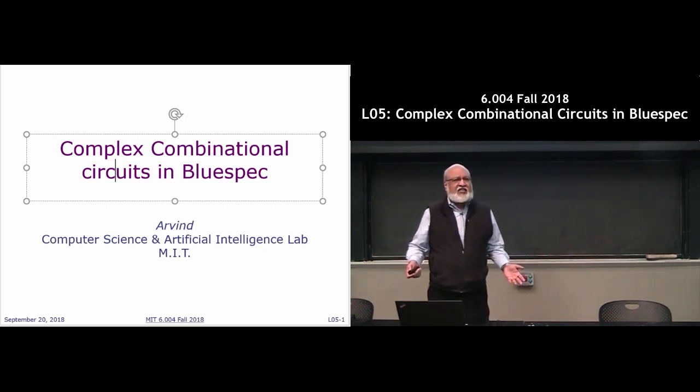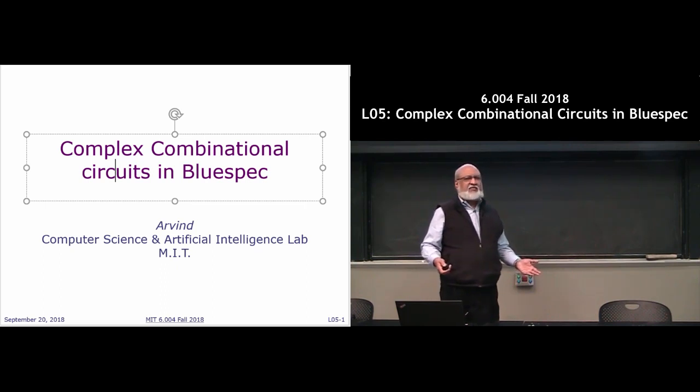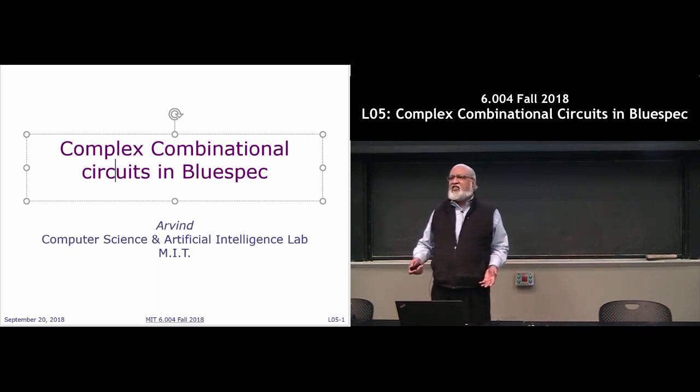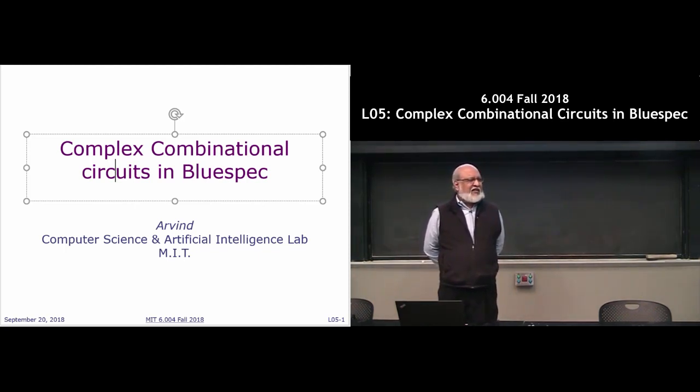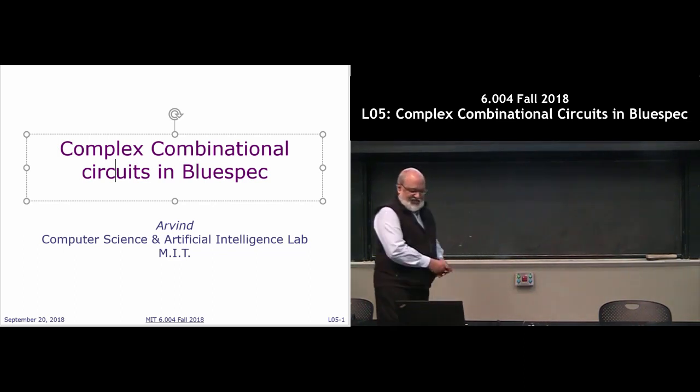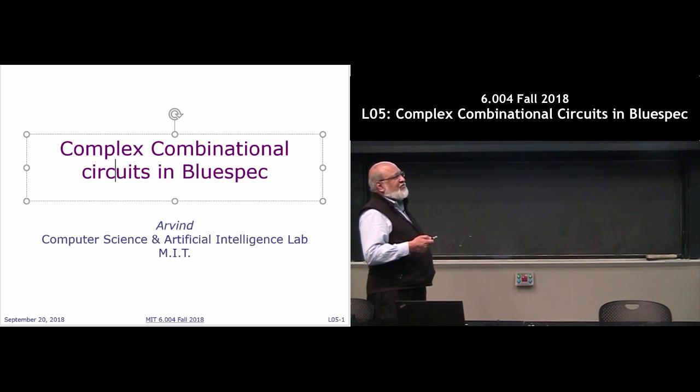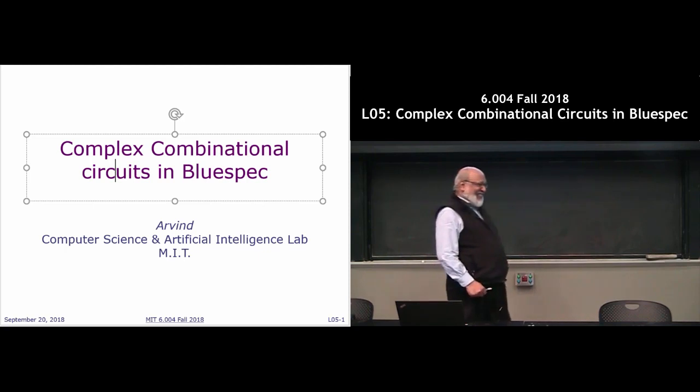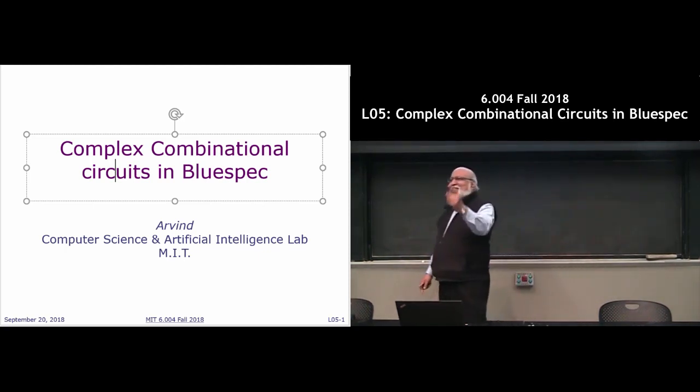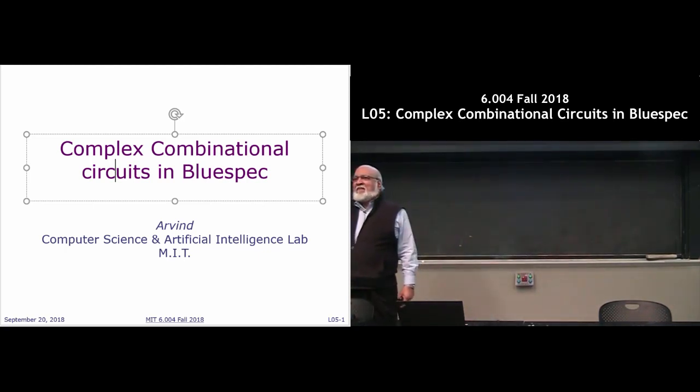So how does the compiler decide what the size is? How does it know that you are trying to build a 3-bit adder? Add n is parameterized by W. So if you give it an x or a y, it'll check how many bits it has, and using that assign the value to W. No. Okay, good try. Anybody else? How do you know? Yes. Sorry, say that again? Recursion.